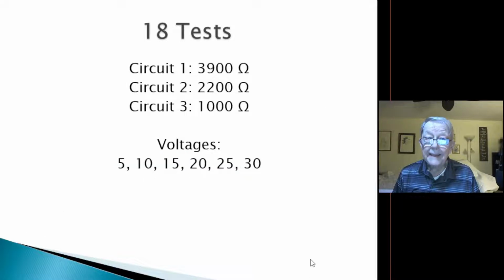Okay, so I did 18 tests. I had three resistors. The first one was 3,900 ohm. Second one was 2,200, and then 1K. I select one, and then I apply 5 volts to it and measure the voltages.